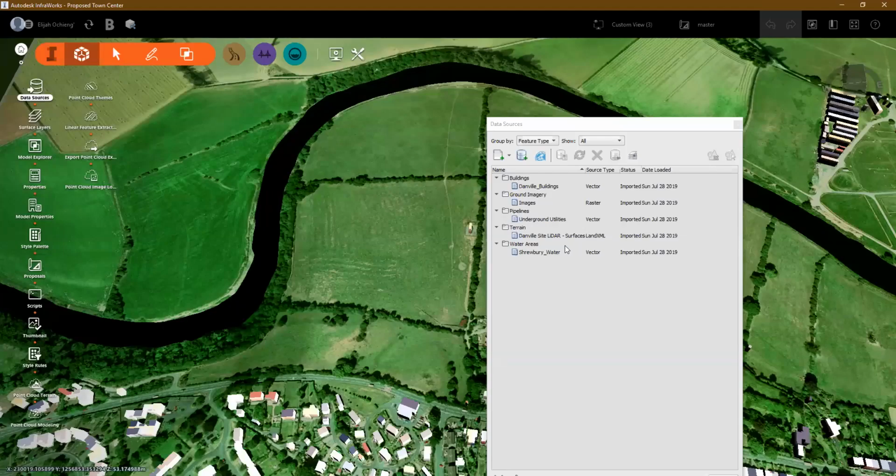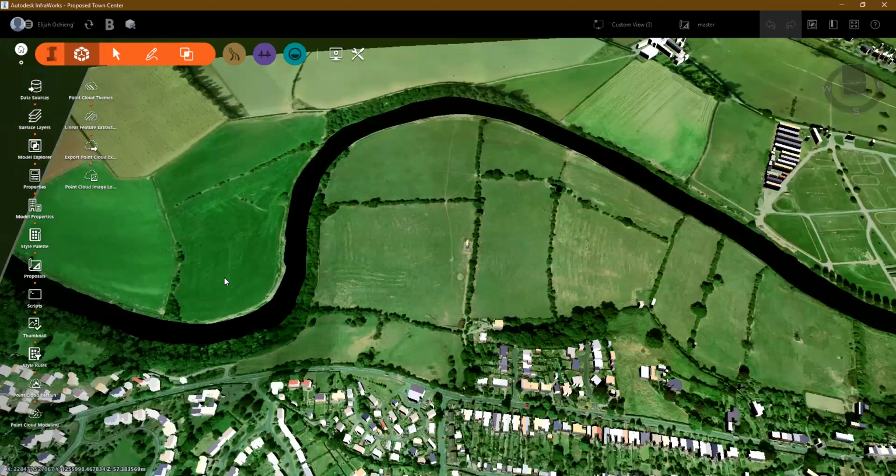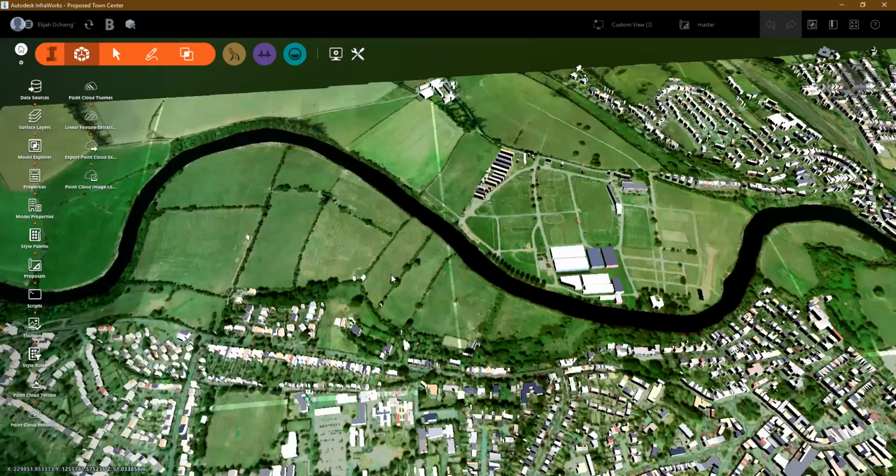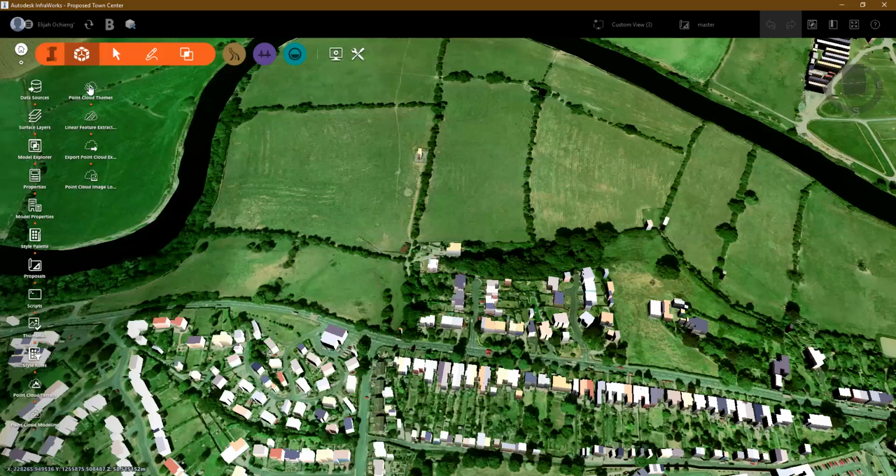If I want to know maybe this is the road reserve, these are the adjacent buildings that the project will affect, then I can now start doing my proposed corridor alignment. So I won't go into that because of time. But you can see the various GIS information that I was able to bring in in terms of the buildings, the images, and even underground utilities in terms of the existing sewer line, the pipe networks, and all those other related project context. So also you can do different design alternatives and come up with the one which is most feasible.